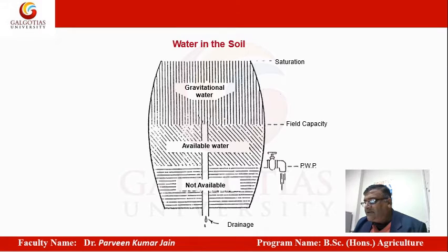Now, beyond this level, the water goes to the permanent wilting point, beyond which the water is not available. In flooded systems, you will have this situation in a cyclic form. For example, you are irrigating today, then you wait the next 5 days for the extra water to go. Then you will have the next 5 days, most probably, of available water.